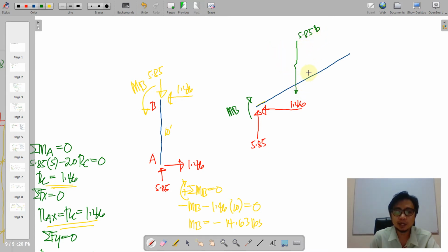So getting the component, remember that this is in pounds force now. Let us get the component parallel and perpendicular to the member. Actually, we have these two components of this 5.85. Of course, we need an angle here, so that if this is theta, and that is also theta. Okay, so inclined angle and then perpendicular and vertical, that is also the angle. So why do we need to do this? Because this is our reference in getting your components of 5.85. So it is just a matter of determining what is the adjacent side and what is the opposite side. So it is obvious that the adjacent side here is this one. So if we have an adjacent side, then our multiplier is cosine. And I think your angle is 45 degrees. So about this component is actually can be projected on this. Isn't it that they are just parallel? Okay.